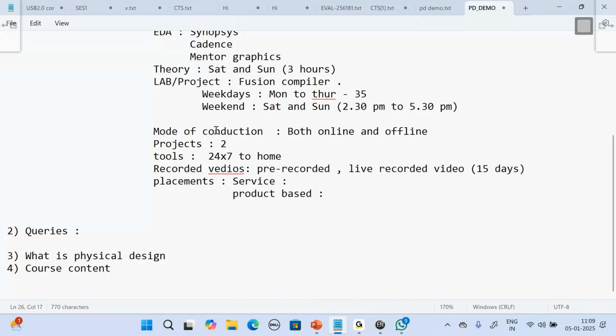If you want to write an automation TCL program, then how do you find the connections from the port to the cells? What command do I have to use to do that? After knowing all these things, if you write a TCL program in just half an hour and execute it, all these cells will be pulled near to the port. So this totally depends upon your coding skills, how you can do the TCL, right?